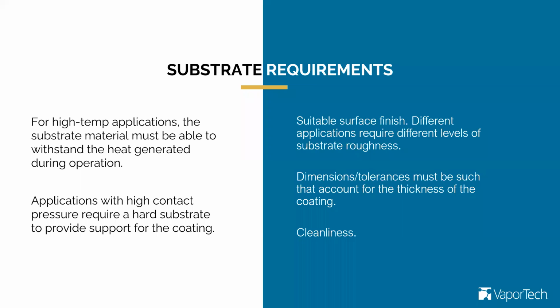These coatings that we're talking about here are in the range of 1 to 5, 6 microns, right? A single strand of hair is about 50 microns, depending on the person. So you can imagine that the film that we're putting on top is 10 times thinner than that. Deformation of the substrate can get to a point where you can fracture the coating itself. So the substrate has to have enough hardness to support the coating, right? It's called load bearing capacity.